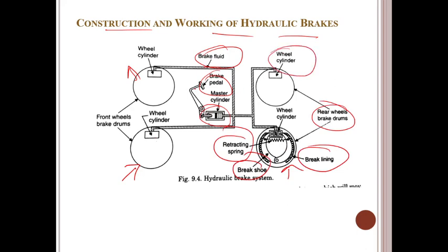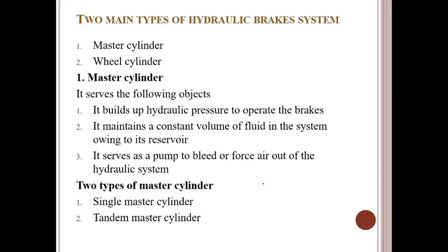Whenever the brake pedal is applied, all the pressure from this master cylinder is transferred equally to the fluid present inside these pipelines. Whenever we apply pressure, the pressure is equal to force upon area. So the force acts through this braking system on the wheels, and the wheel will be stopped. The pressure is transported equally through the fluid to this side and this side, and our braking system is applied. The vehicle stops, guys.